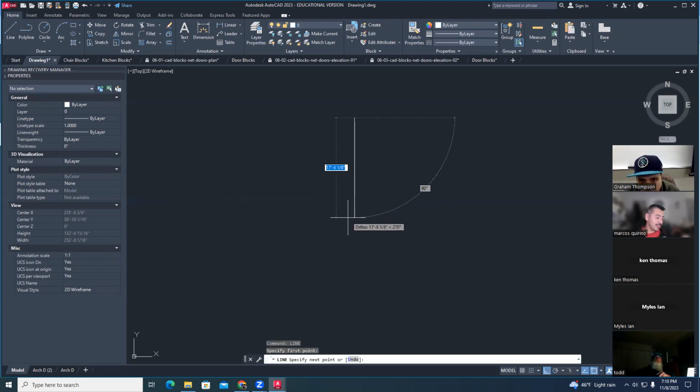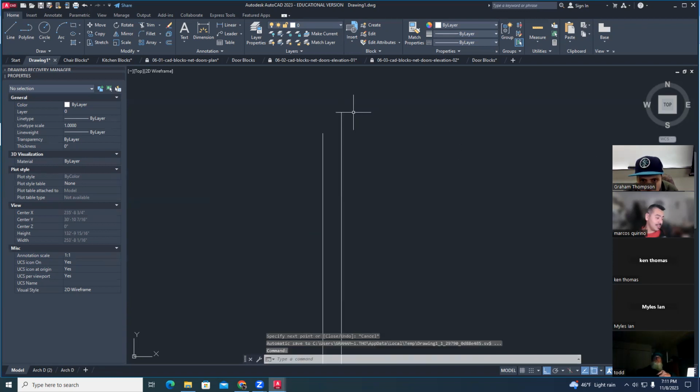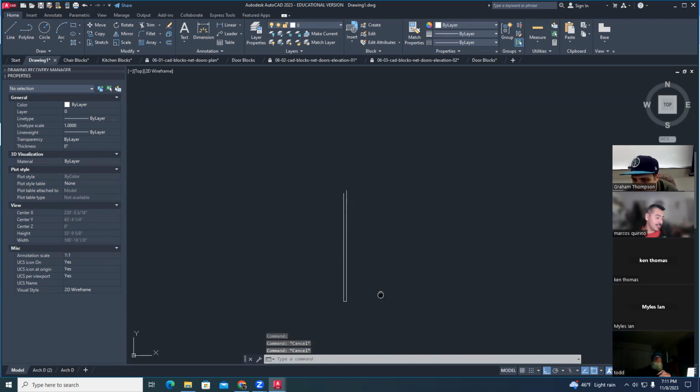For our sake, we're going to be on the east side, but I'd like to have your east wall drawn in plan view. Whether the whole building's drawn or not, I don't care, but I want an east wall of an exterior in plan view. Then I'm going to show you a couple things on transferring a side wall into a profile.